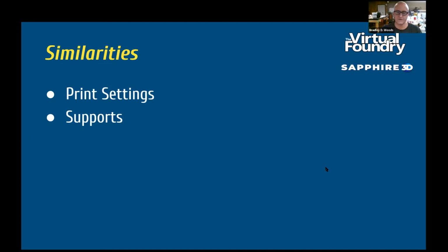Sure. When we tell people when they first start to set the printer up with PLA, and this is if they haven't worked with our materials before, get everything working with PLA, prove that you can print, and make two changes to the settings. This would be the default settings in Cura, for example. Just pick the default generic PLA and raise the temperature to 220-ish. I think it defaults to 200. You likely have better luck around 220, 215. And the only other change you need to make is the flow rate.